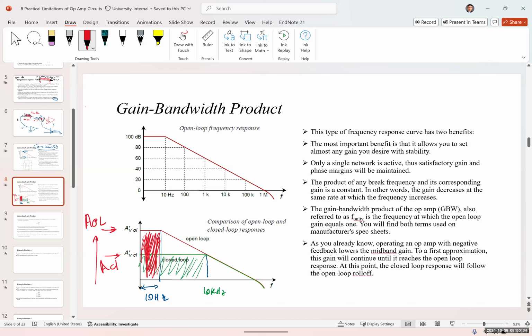So depending on the op amp, we have some power over controlling the bandwidth, but again, that is limited by the op amp as well. If an op amp has a limited gain bandwidth product to begin with, you would have limited bandwidth to work with at the end.